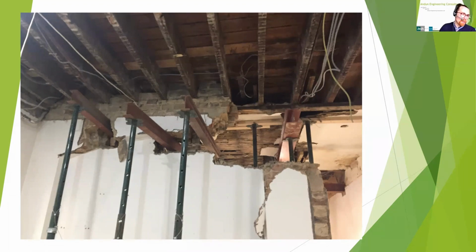What we usually recommend is that there's a U head or something similar when you're using acro props, so that you can make sure the prop head remains attached to the header, so it can't be knocked out accidentally. There's no such thing here, and it's also dubious how much bearing the wall has got onto the lintels that have been installed.